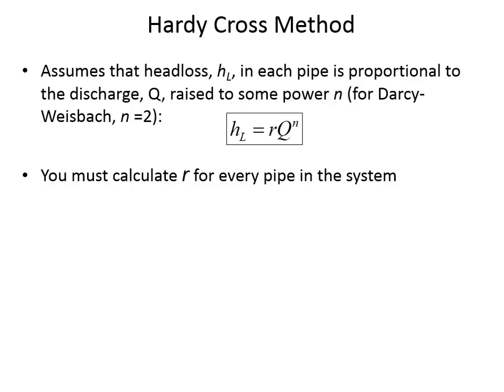But if you were using the Hazen-Williams equation, area is still, if you want to find velocity, it's still Q divided by A. And so V squared, we do Q divided by A squared. So your point, you're asking, if we're going to do V to the 1.85, why wouldn't it be Q to the 1.85 and A to the 1.85? That's your question? I'll have to think about that and get back to you. I'm not sure. But the good news is that that issue won't affect us because we're going to use Darcy-Weisbach.